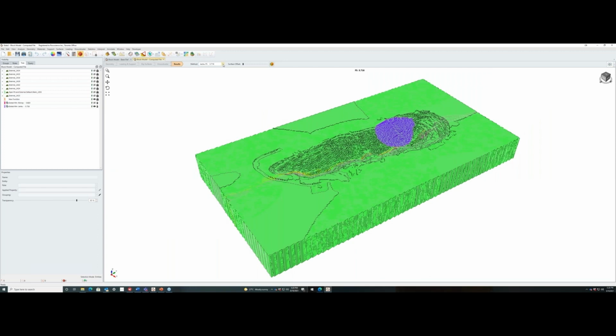Right now we are looking at the Janbu failure surface. I can switch to the Bishop. The Bishop factor of safety is 3.8. The Janbu was 3.72. So these are the results we got from using the block model. I am now going to show you the same model, but using the complete model. And let's see how the results compare.